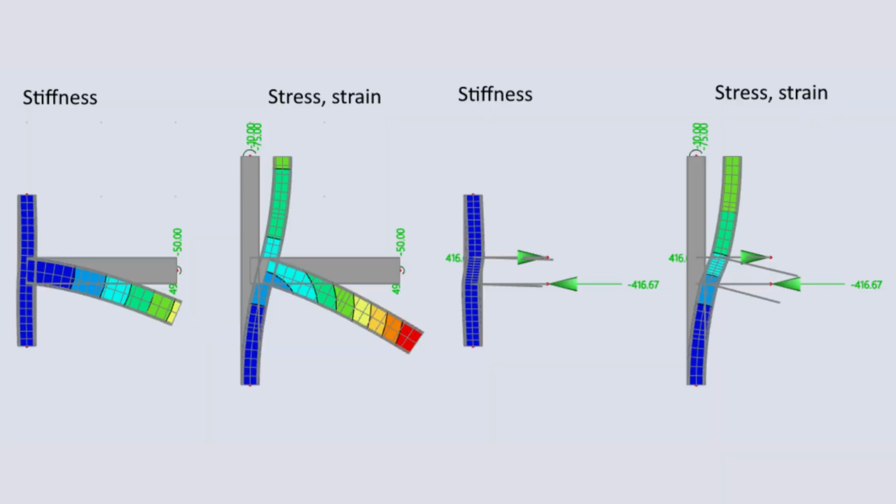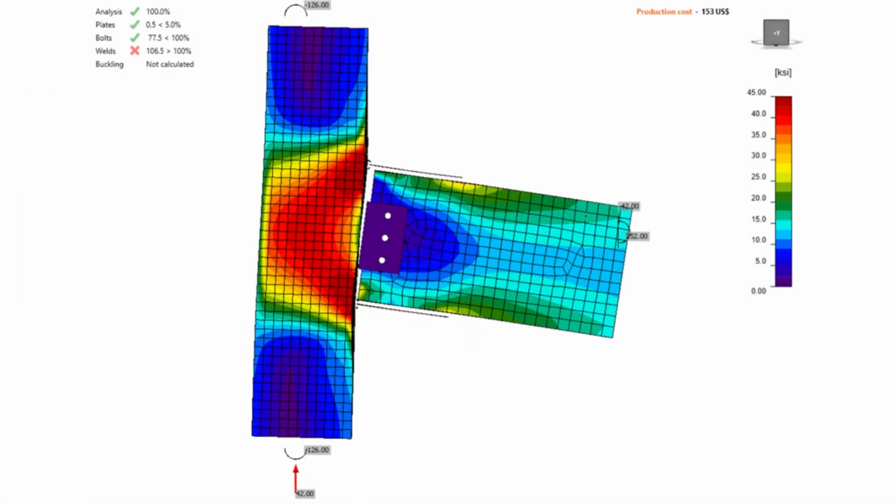Understanding the load path is essential because every component along that path must have sufficient strength and stiffness. If the engineer misunderstands how forces move through the connection, it becomes easy to overlook a critical limit state or unintentionally overload a component. The load path also helps engineers interpret analysis results more intelligently. Analysis software can produce a tremendous amount of information, but the engineer still needs a mental model of how the connection should behave in order to judge whether the results are reasonable.